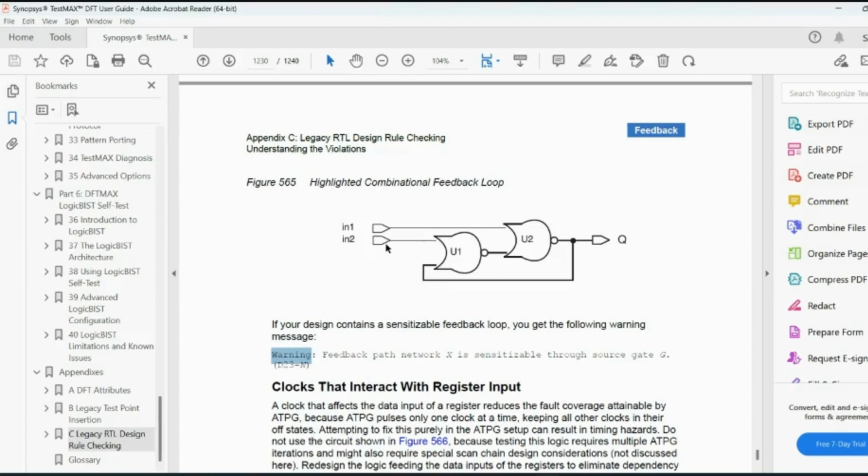In this stage, this particular NOR, if you fix the other input to 0, what are the faults you can cover? Here 0 and 1 will be fixed. Here, in this particular line, one 0 fault is fixed. I mean, you are already targeting the 0 fault by forcing the value to 0.